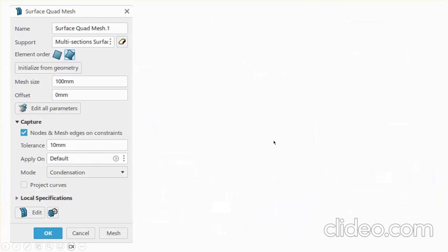Now, when it comes to meshing, each of these surfaces that I have created, and there's 14 of them, 15 including that top extrusion one, each one of them is going to create a mesh, and if you don't ask for the nodes at the interface to be merged together, obviously they're not connected to each other. And you have to do some other trick, coupling, etc., to do it.